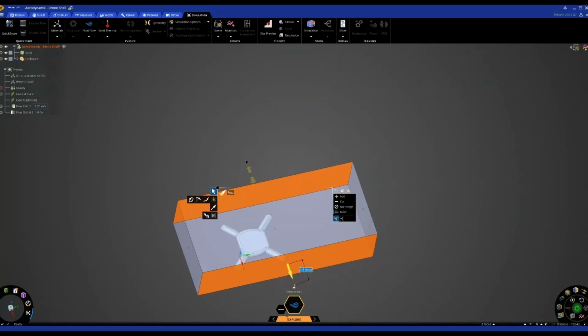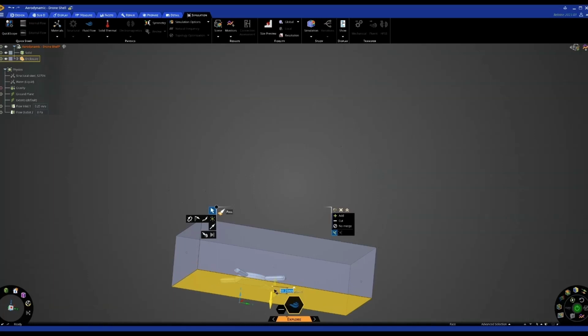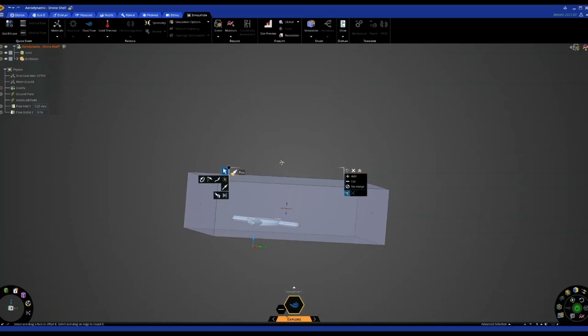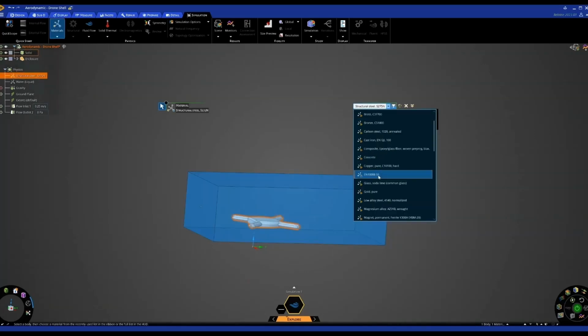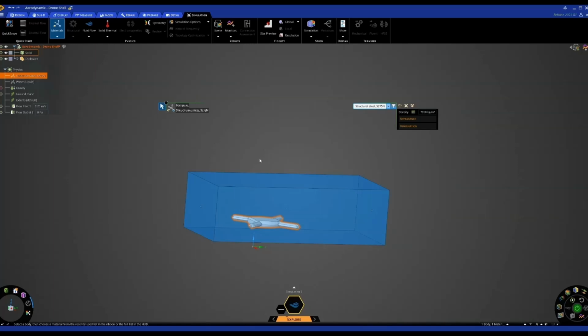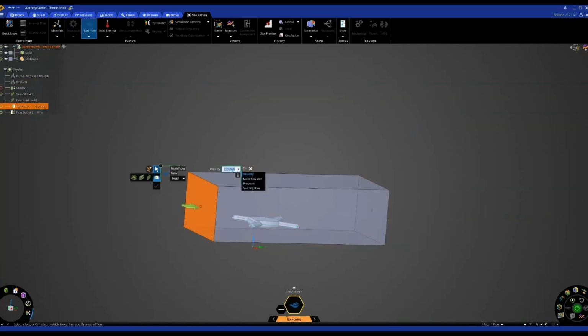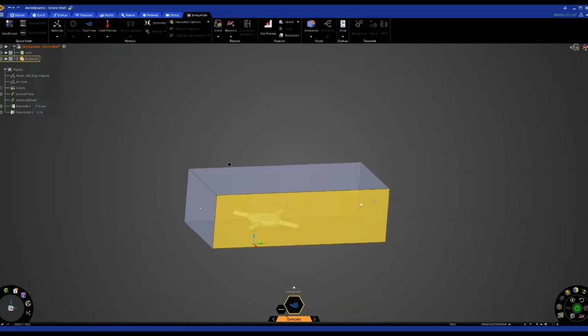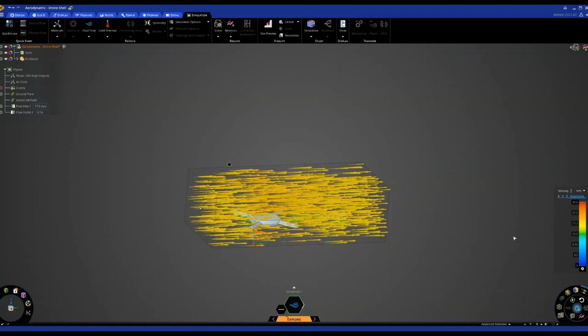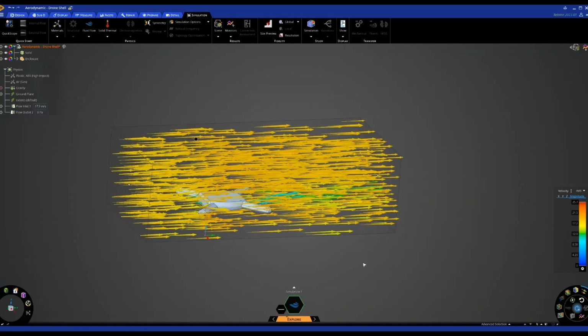You can go a bit smaller. Let's just make that ground plane off the body. And change our setup again. So let's just change that to ABS. And our water to air. Change our inlet speed lastly to 40 miles an hour, same as before. And you can always create your own fluid volume as well and do this manually without the quick start guide. But very quickly, within a few seconds, we'll start to get more results on a more aerodynamic part.